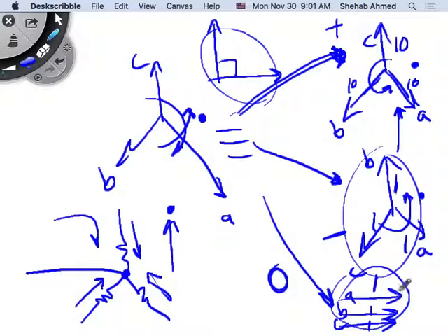But now I have these 3 in-phase voltage supplies that are not going to create a rotating MMF, but they're going to create current in the motor. This current will create torque. That torque is not going to rotate. It's stationary torque, right? So this can plug the motor, can break the motor. This can rotate in the opposite direction, and this will rotate in the direction you want it to rotate. So if you have too much of the negative sequence or too much of the zero sequence, it's a problem.